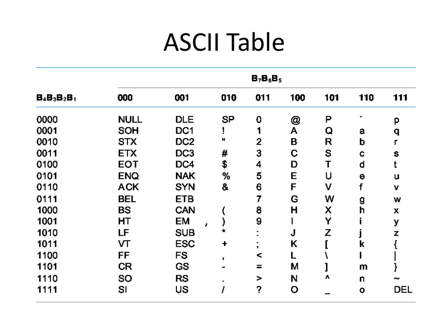This is the ASCII table, with various types of characters. Here the least significant bits are B1, B2, B3, B4, and here B7, B6, B5. To determine the null character, we have to select 0000, and from here 000. To select DLE, the row is 0000, and the last is 0001.